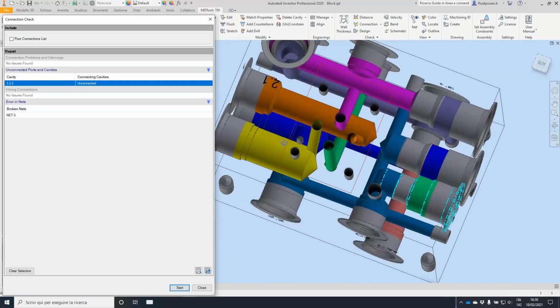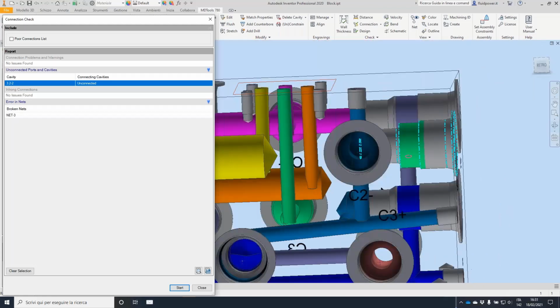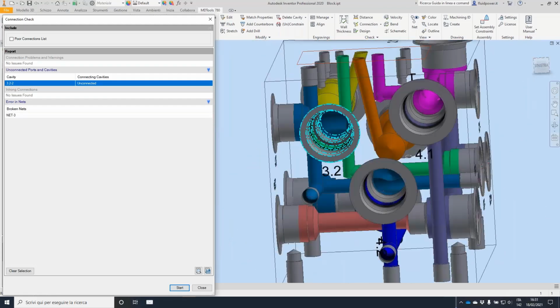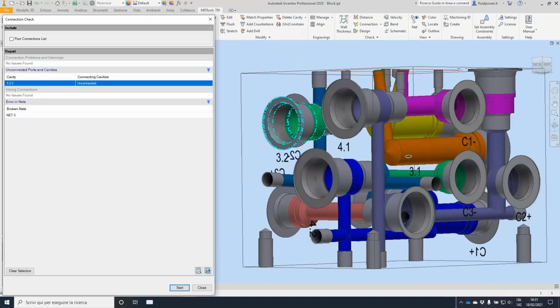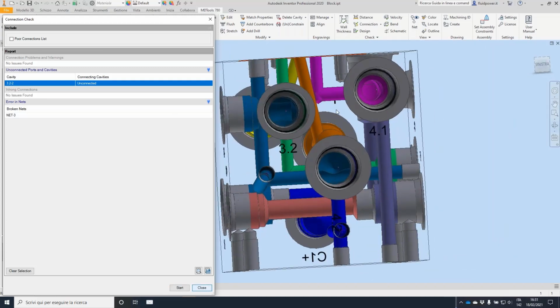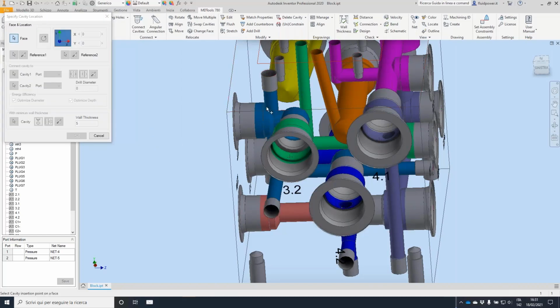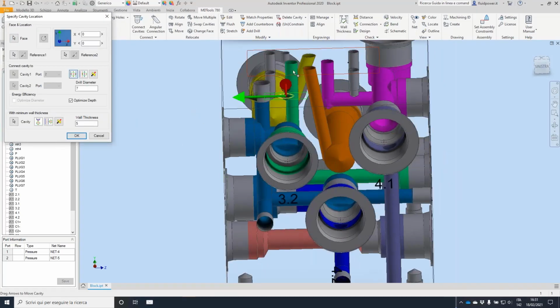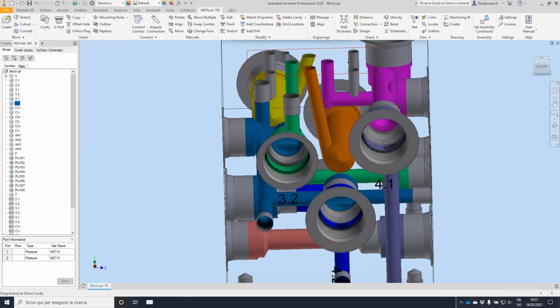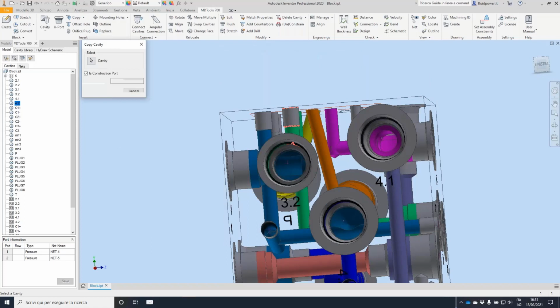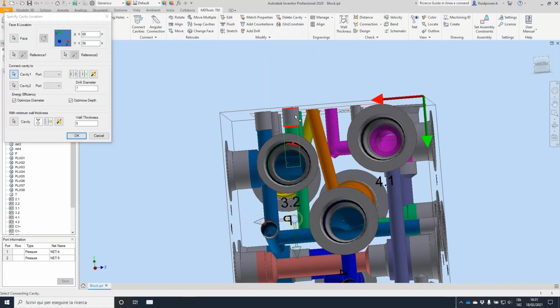It's almost finished, but the green net is not completed. So we'll need to find a solution for that, and we do also now all the connections that are needed. Yes, I found a way to make the connection. Let me create a construction plug on port 2 on top. And let me take reference to the green drill that is behind. Reference with this one, at 0 mm. So it's center to center, and we copy and do the connection this with this one.